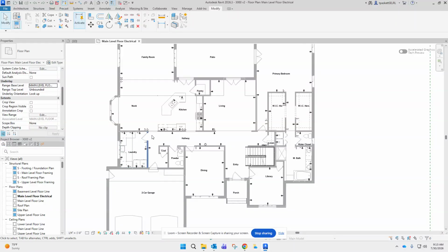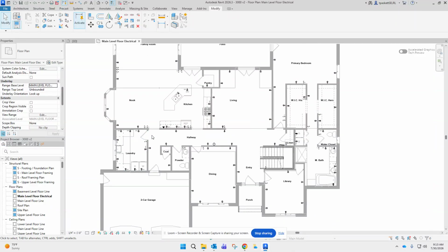Smoke detectors need to be in the following areas. You need one in every hallway, you need one in every bedroom, you need one per floor, and you need them over the stairs. A lot of that can be overlapped. So the hallway and the per floor, that's the same, that covers it all once. But what that does mean is that if you have an unfinished basement, you have to have a smoke detector in that basement. Even though there's no hallways, there's no rooms, you still have to have one there.